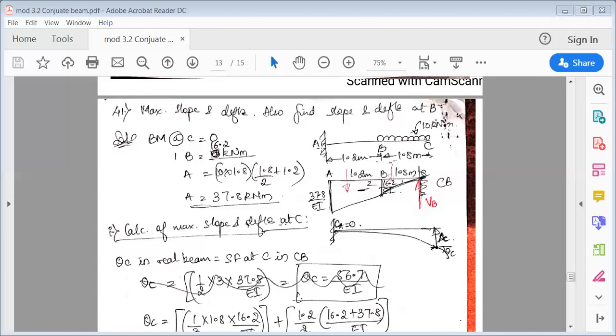Similarly, bending moment at A. Now, bending moment at A, you have to find out between A to B there is no load. So again, this UDL 10 into 1.8 into 1.8 divided by 2, so you're at this level. Next, because you're finding bending moment at A, you have to add this 1.2 here. So 10 into 1.8 is the load, then the complete distance is 1.8 divided by 2 plus 1.2. So when you solve this, you'll get this bending moment is maximum at A.